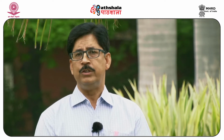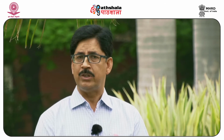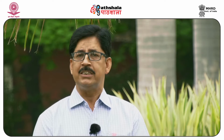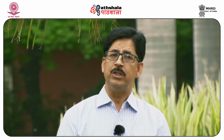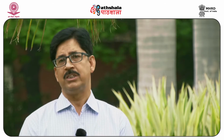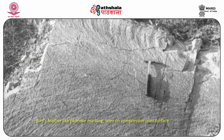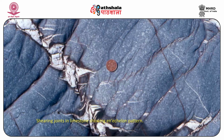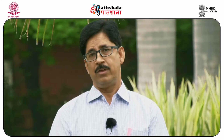Without joints, we do not have any rock present in natural conditions. You may not have shear zones, folds or faults at a particular site, but it is very difficult to find any rock mass without joints. So joints are going to play the most important role apart from the contacts.